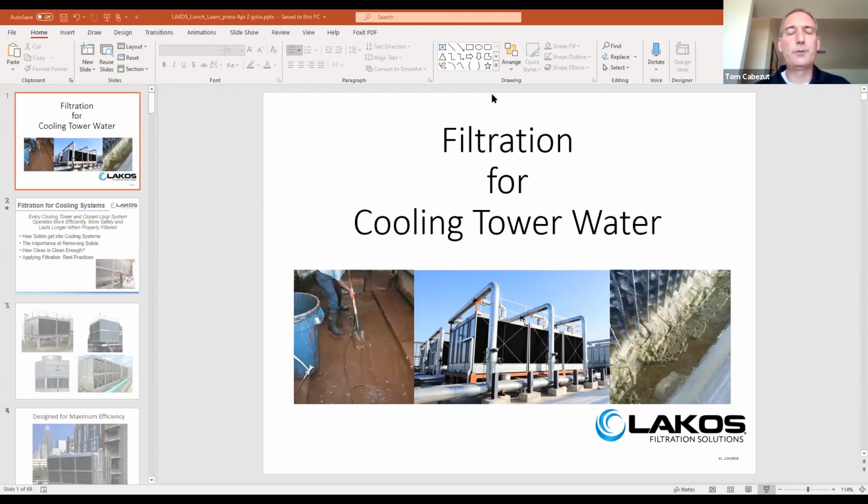So cooling towers and closed circuit coolers, obviously most of you know the difference. One has a lot of fill in it and there's no coil in it. And the other one has the coil that you just recirculate water over. But the basins act the same way. I've actually seen multiple installations, and one of them is down in your area, where they didn't equalize them, and we are overflowing one to the other. So equalizers are still required if you're using closed circuit coolers versus open cooling towers. All right. Hopefully that answered your question, Kevin.